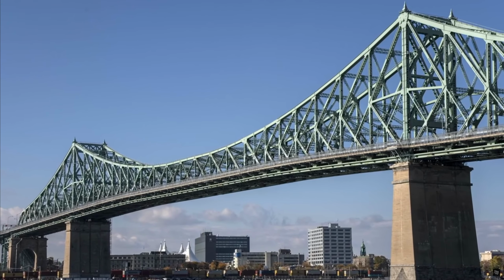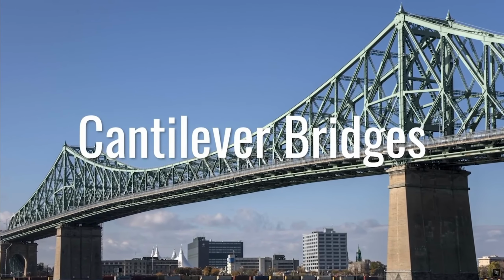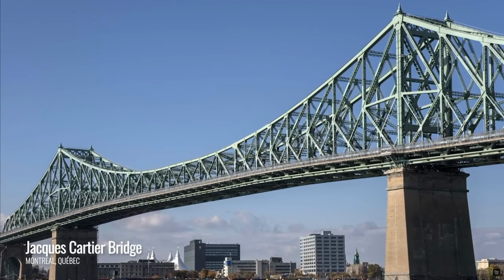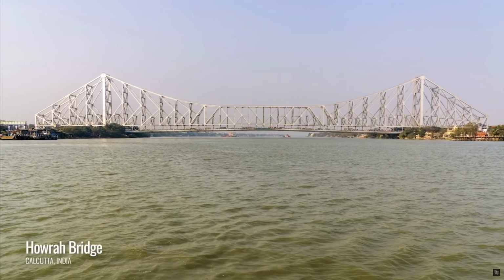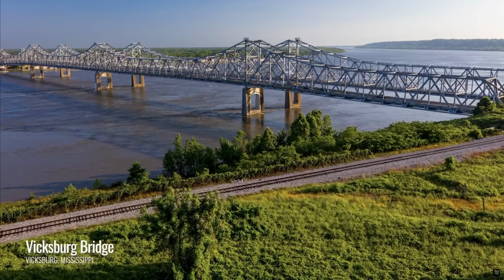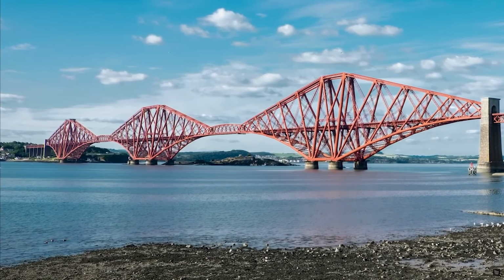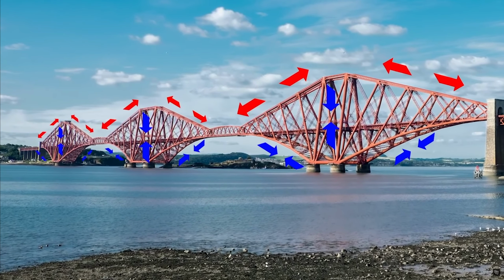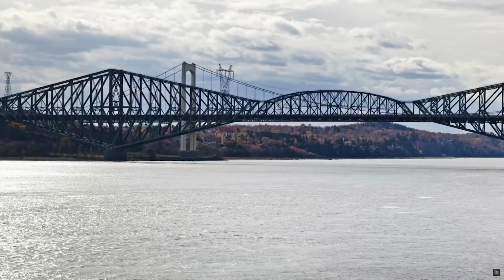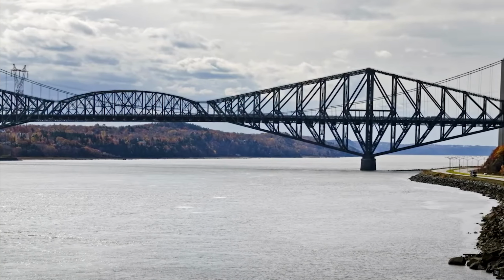What type of bridge is this? So a cantilever is a structure that is supported on one end, where there is a fixed side or support, whether beams or other types of support members that are resisting the rotation of the deck. And so it is incredibly important to make sure that the fixed end is strong enough and that the flexing extended member has the ability to resist the tension on the top and the compression on the bottom. Perhaps the longest cantilever bridge is the Pont de Québec, the Quebec Bridge, there in Quebec, Canada.